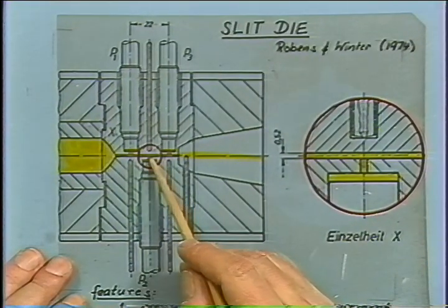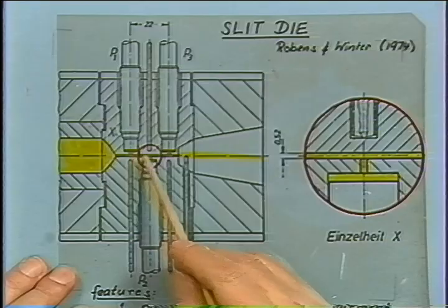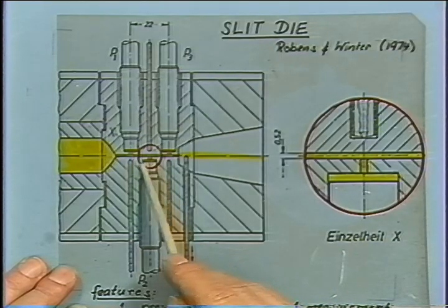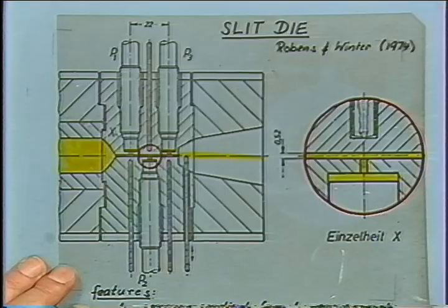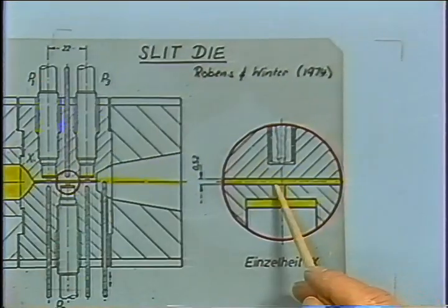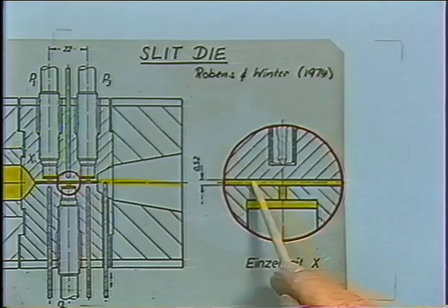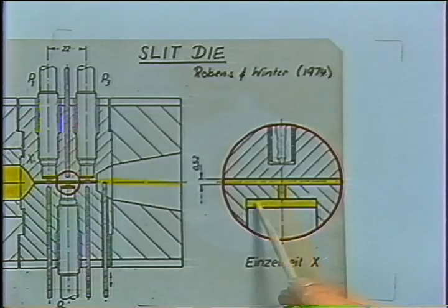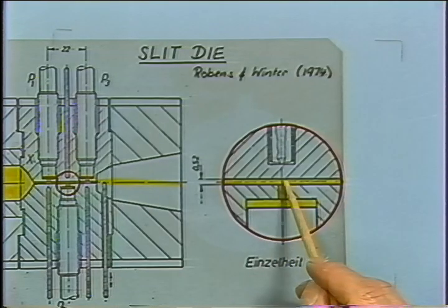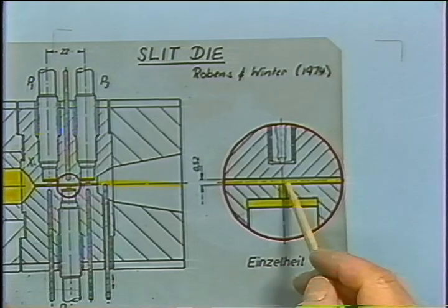I added here those pressure transducers with small holes. The transducer itself is too big to be mounted on this space-sensitive slit, so we have just a small hole here. This is a blow-up version, a small hole. This is the flow channel. And the pressure in this cavity here, which is connected to the membrane of the transducer, is equal to the pressure out here in the channel.